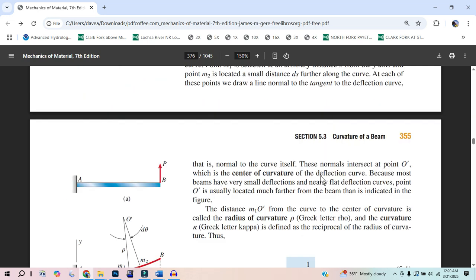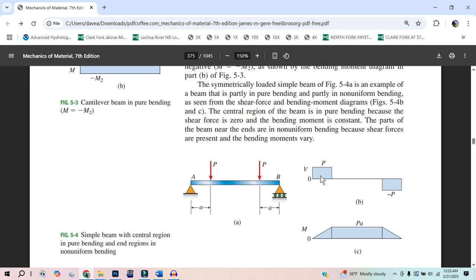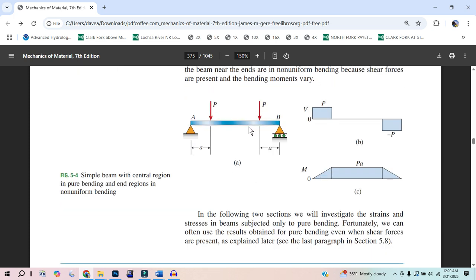But that is a huge take-home point for this chapter, that we are taking this moment, and this is the driving. And this chapter doesn't even cover deflections. It just says, when we get that crunched shape on top and lengthened shape on bottom, we can know what the pressures are. And those pressures will get a number, and we just want to make sure those numbers are smaller than the actual pressure that steel can take. 58,000 pounds in compression.